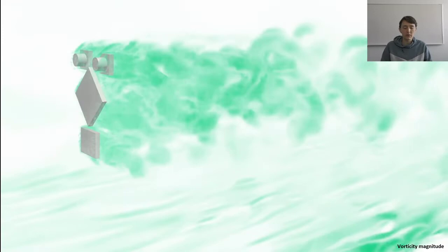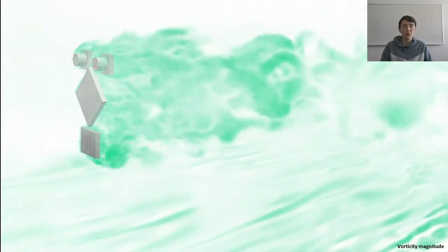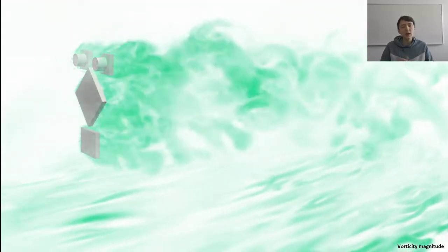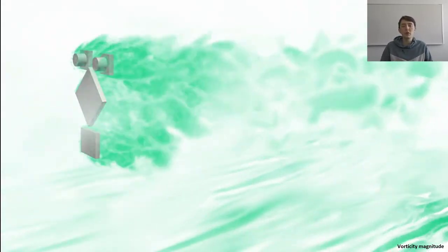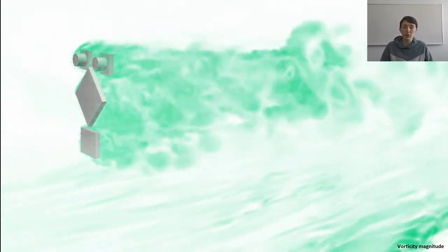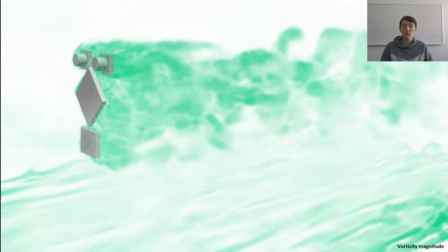And that's when they asked the University of Minnesota to have a look with them and see what could be optimized. So in our research group we focus on finite element methods, and naturally we used a finite element method for handling this problem. Now that is not very usual though, because if you're slightly familiar with computational methods for fluid mechanics, then the method that we typically would use is a finite volume method.